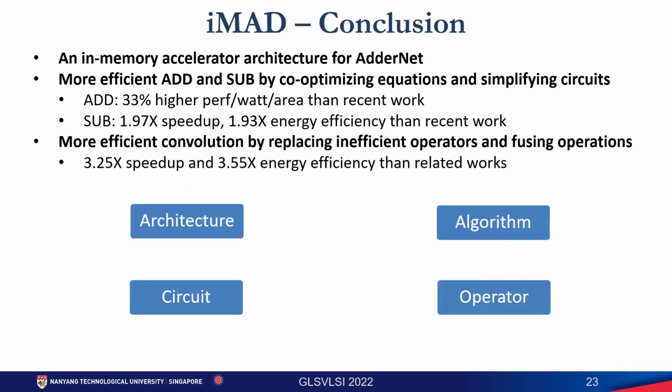In conclusion, we have built an in-memory accelerator for AdderNet. We realized the more efficient addition and subtraction operations by co-optimizing the equations and simplifying the circuits. We have achieved the more efficient AdderNet convolution by replacing the inefficient subtractions with additions and fusing operators. Evaluation results show that our proposed methods are effective.